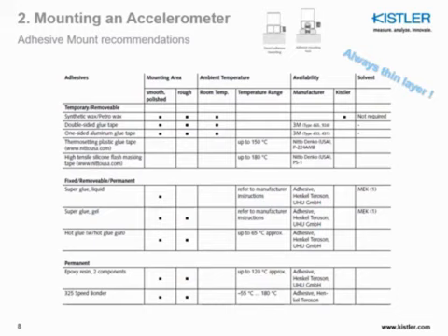Here in this table, we are giving you some examples of adhesives that can be used. Whatever adhesive you choose, remember to always use a thin layer as much as possible to avoid any damping that could then lead to a lower frequency response.